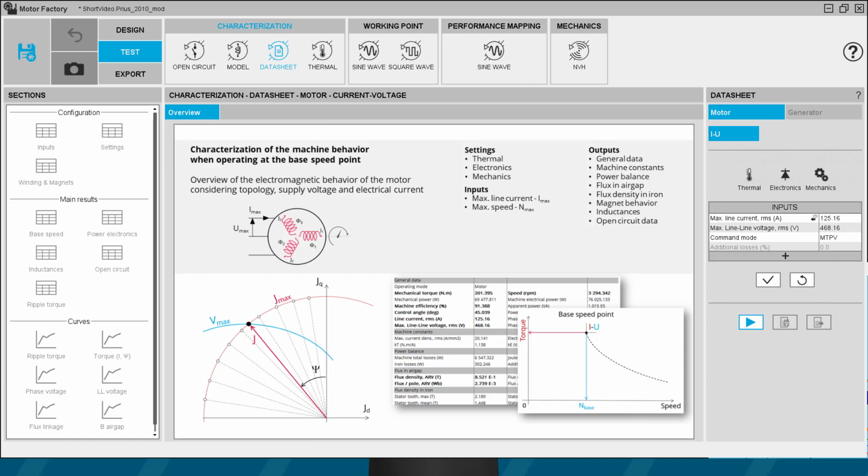So the magnetic flux density is also computed in every part of the machine to evaluate the design. The test results also include all the necessary constants to build the equivalent model of the machine and to simulate the behavior of the machine in its electrical environment. An overview of the machine performance at no load is also given in this test.